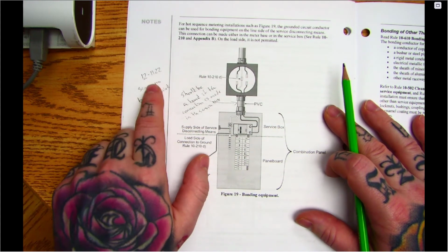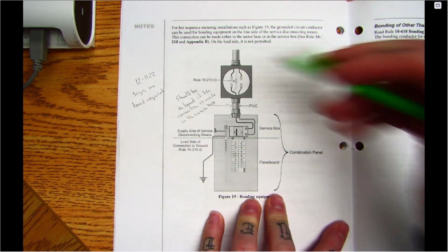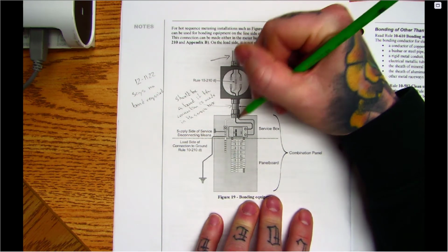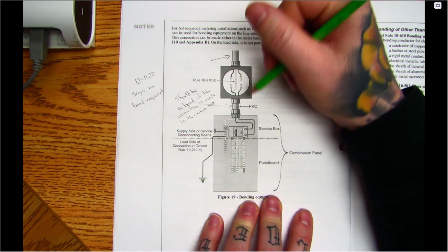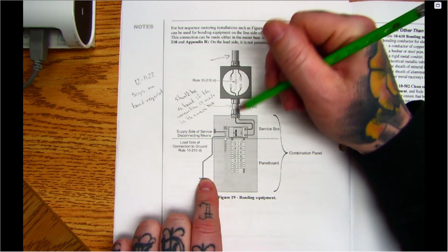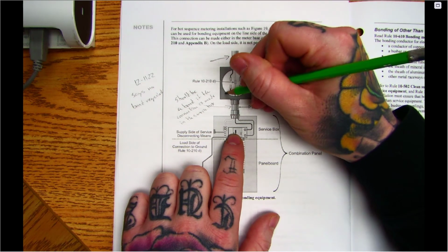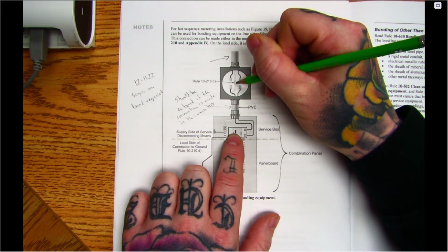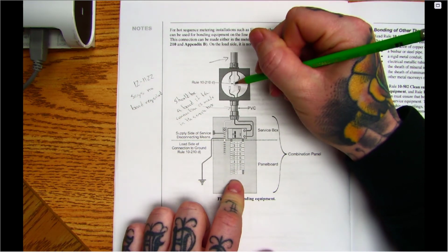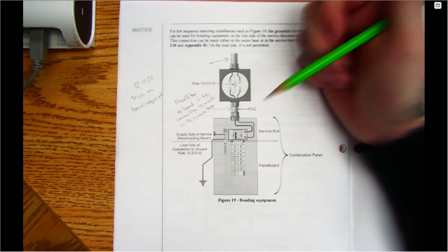This example here too, just a heads up. It says later, in Rule 12, this is in wiring methods, that we don't have to have a bonding conductor in the PVC. It says we don't have to have one up here, up to the service mast. We definitely should have one here. So they don't have one in this picture. Regardless of whether we're grounding it here or up here, we definitely have to have a bond going through here to carry our bond. Otherwise, in this case right now, this is not bonded, because this should be isolated according to the new code. If it's being grounded here, the grounded circuit conductor should be isolated, and then we should have a bond going up here. Okay, so just watch that picture so it doesn't confuse you.